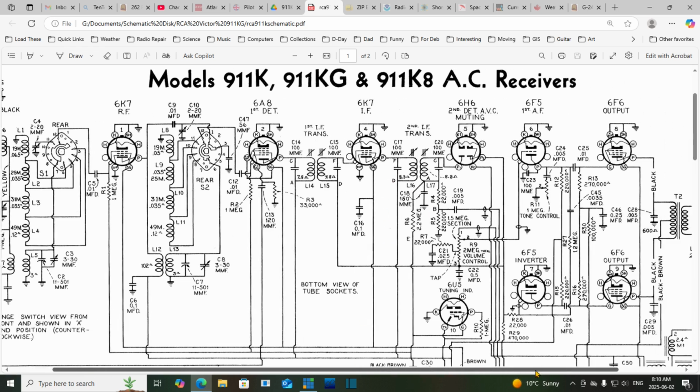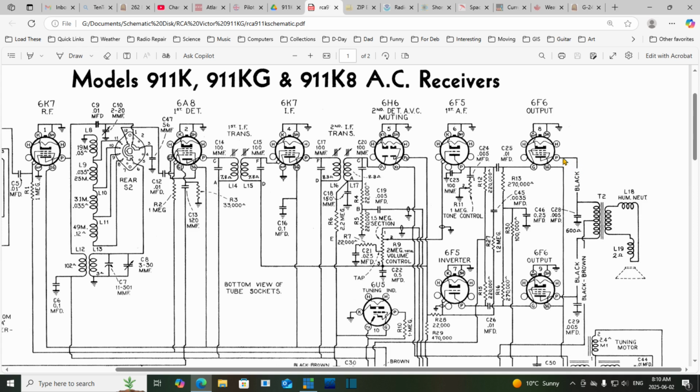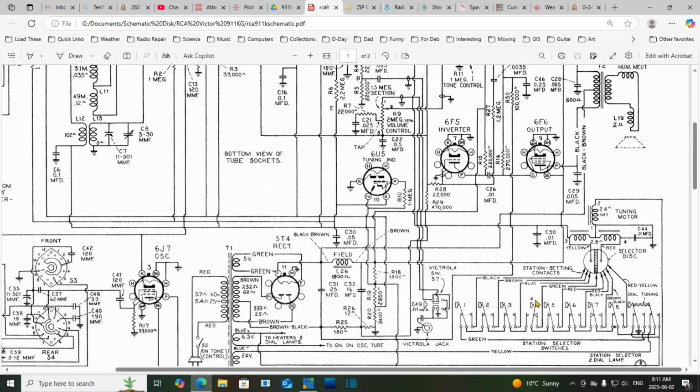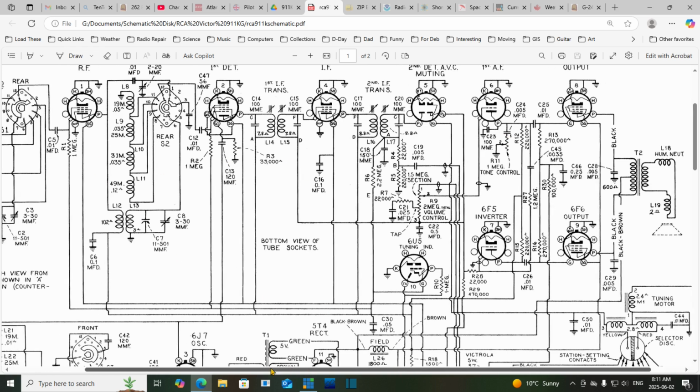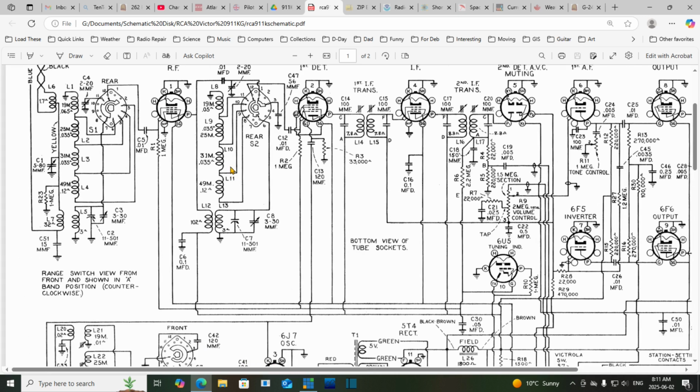If we come back to the audio circuits, which I should have dealt with already, what are they doing here with the screen? So there's the screen, SG, screen grid. Another one, come down here. So it has no special capacitor on it, and it's probably because this is an output tube and it's not so required here at this point. That's what I would suggest. Okay, so the screen thing's going nowhere. I've already done it. What would be next?